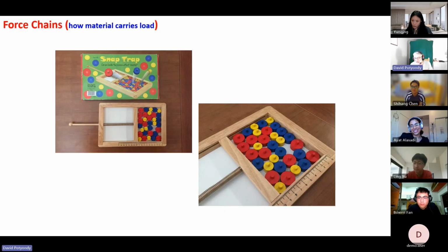Oh, absolutely. So the force chains are a function of shape. Correct. They're a function of friction coefficient, shape, and size distribution. And this is showing it's a function of size distribution. If you make all the discs exactly the same size, they will not have this arbitrary packing. They will perfectly align along the walls, and then there'll be another aligned system that fits in the chinks, and you'll get this crystalline arrangement. That will behave very differently than a heterogeneous arrangement.